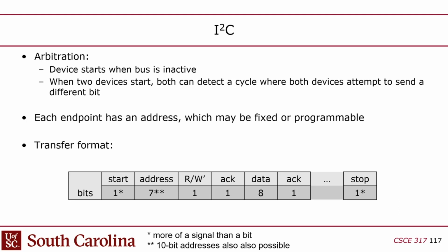The way it works is that the slave actually takes over control of the data wire. The data wire gets time division multiplexed, so that after I put the address out, the slave gets control of it and then sends the acknowledgement. I use the wire as an output for the address and the flag, and then I wait for someone else to drive an acknowledgement. And the acknowledgement is 0, which means that if no one acknowledges, remember the default state of that wire is going to be 1.